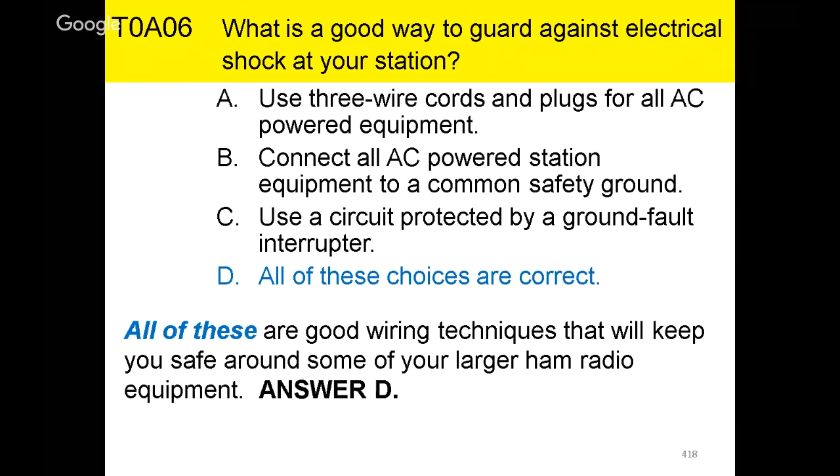They are good wiring techniques, and one of the things I had to do was ground the cabinet of my HT40. Eventually I got around to it after about a dozen or so times of getting a little mild shock. I said, "Well, it's time to ground this thing," so I did. So good wiring techniques are really good to know to keep you safe from some of these things.